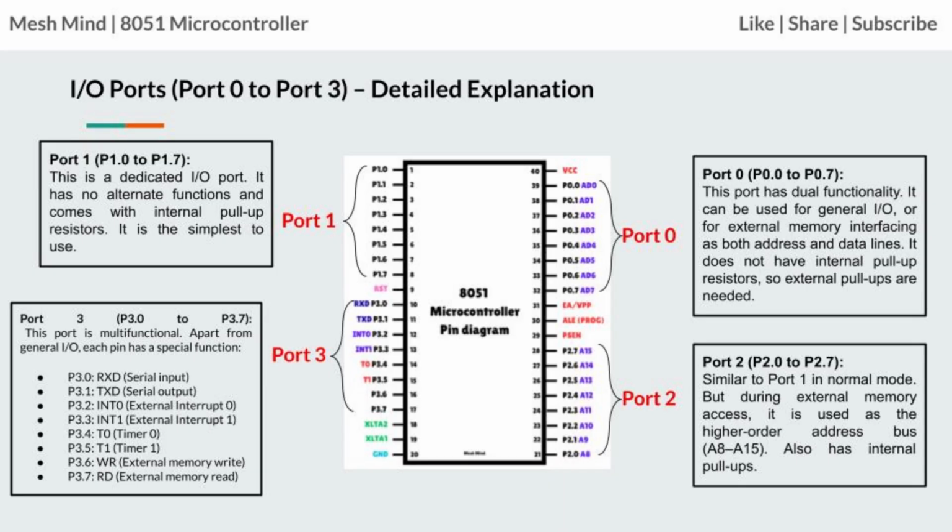Then port 3, P3.0 to P3.7. This port is multifunctional. Apart from general input-output, each pin has a special function. P3.0 serial input, P3.1 serial output, P3.2 external interrupt 0, P3.3 external interrupt 1, P3.4 timer 0, P3.5 timer 1, P3.6 external memory write, P3.7 external memory read.